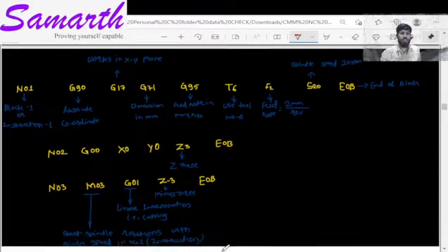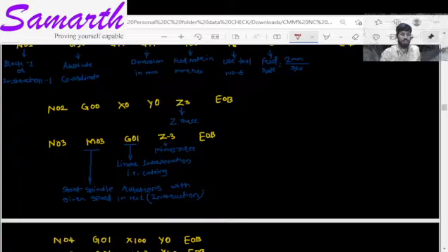Similarly, we will give further instruction M03. Here we have given the instruction to start the spindle. G01 is linear cutting, that means linear interpolation should be done. Z3, then the tool should go to the -3 position. That means previously it was somewhat away from the screen. Now we want to travel the tool to the 0, 0, 0 position, right?